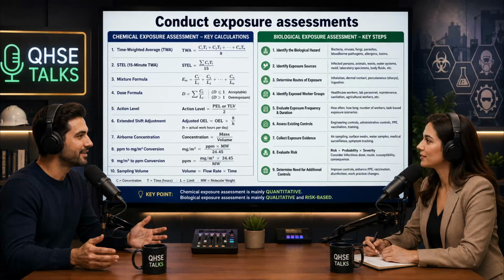All right, we've established the authorities and the baseline philosophy, but how do we actually apply these limits to the chaos of a working day? That's the real challenge. Because an air sample is just a single snapshot in time, but a shift is 8 hours long. The hazard breathes, it fluctuates. So how do we measure the entire narrative of a worker's exposure? We use the foundational metric of the entire discipline, the TWA, or time-weighted average. It averages out the peaks and valleys of airborne contaminants over a conventional 8-hour workday.